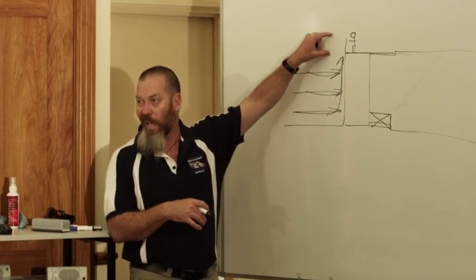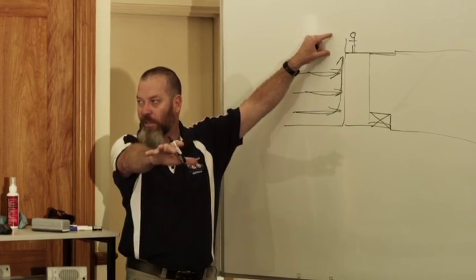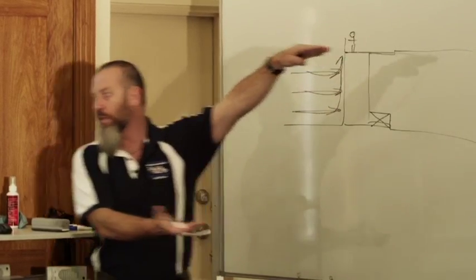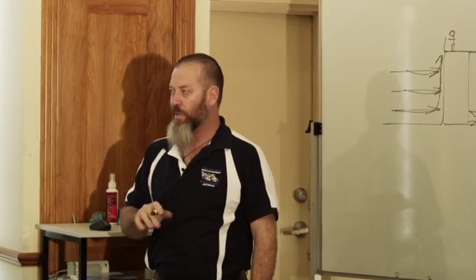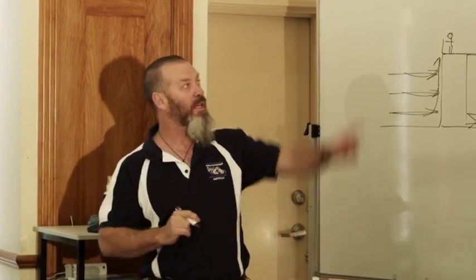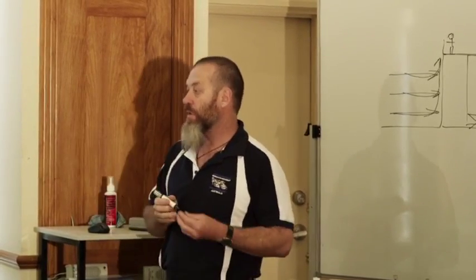So if you're building a house on the top of a hill, what you're getting is all the wind hitting the bottom of the hill, heading up the hill and compressing. So when it gets to the top, it's a higher risk at the top of the hill than it is at the bottom of the hill. So that's why it's important you understand the topographical class.